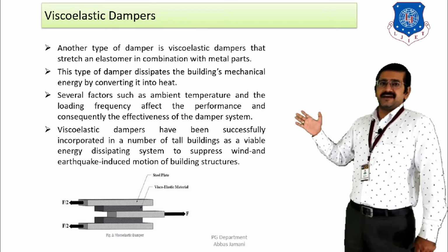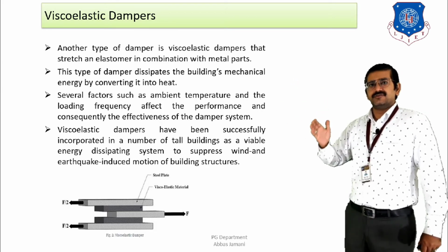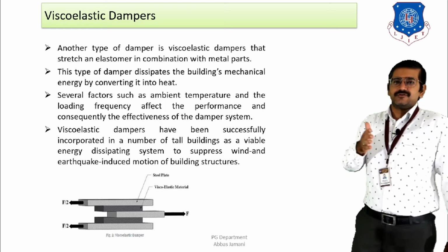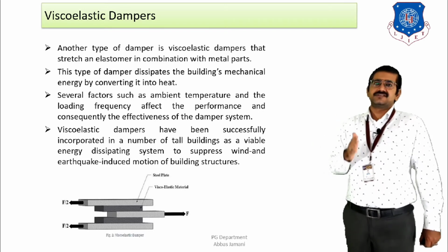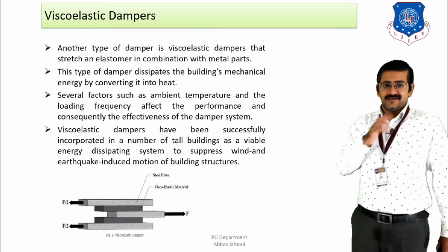Then the connection of the damper with the other lateral load resisting system, from where the load path is going to continue, these elements are also going to carry very little lateral force, and due to this the motion and the displacement of the structure is controlled, or kept within the permissible limit, to a very great extent, right?